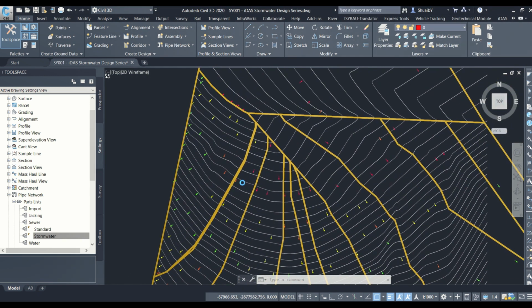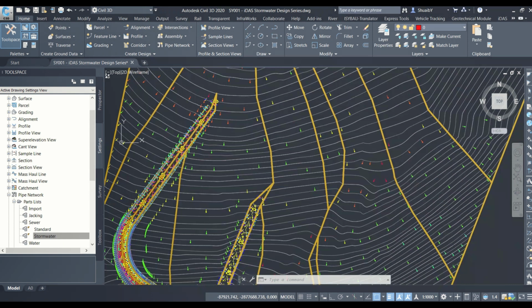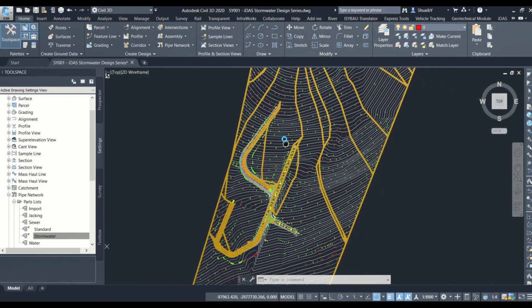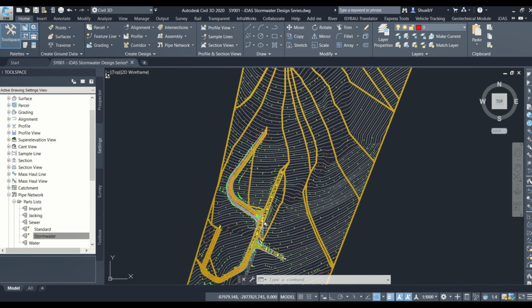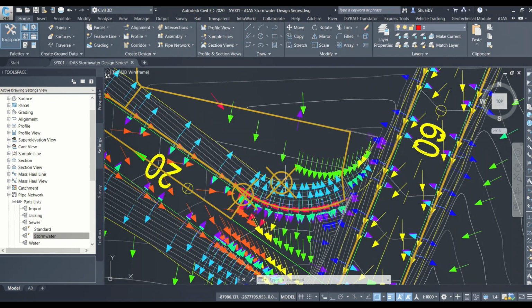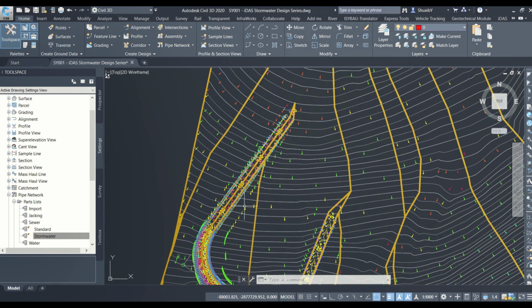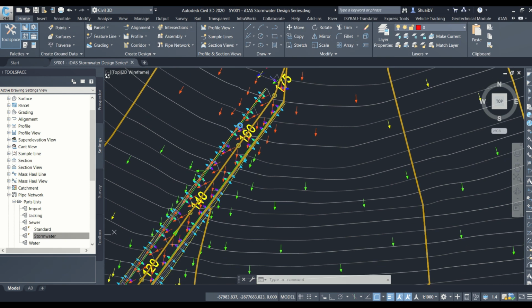And you can see there's a common crest on the top, and this is where the water slopes differently from that point. So you see it's flowing down there, it's flowing down there, and then it's flowing to the side, or it's more slanted or angled that way. And you can see this is where the water is going to come down. Most of the water is going to be flowing away on that side, which is great. But we just have to worry about that row there at the bottom, but it's still draining to the bottom. So it still tallies with the elevation mapping that we had previously. Those symbols indicate that there's a low point there, so that's a draining point. Right, it's really helpful for the inlets, and we're going to use them to help us position them. Okay, and you're going to see just now how we are about to do that.